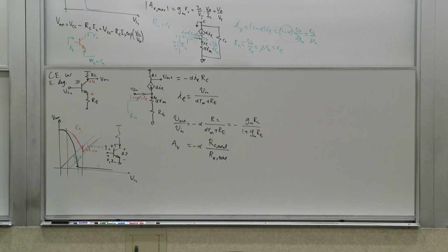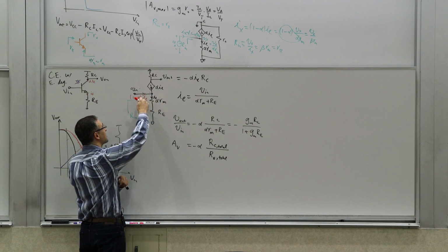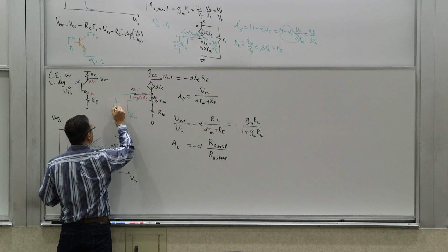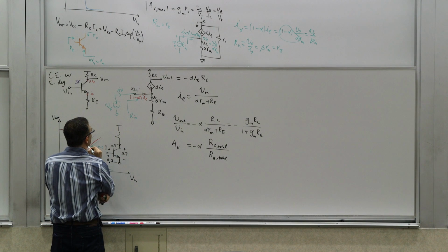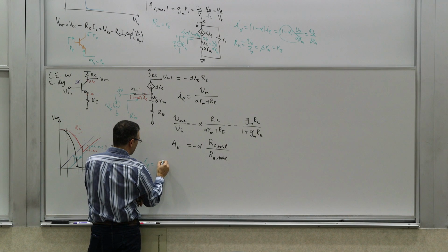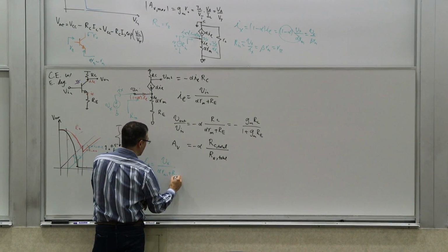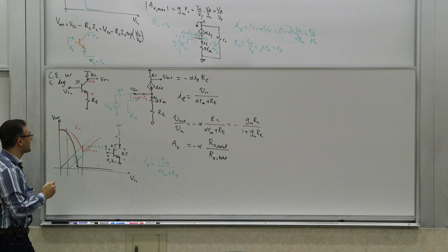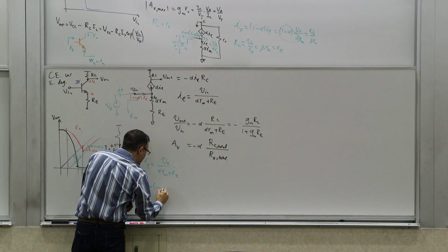Okay, so that's the current. So what does that tell? I have an interesting situation. You have this resistor, and the current through this resistor is clearly determined by this voltage. So if you apply a Vx here, let's say Vin becomes Vx, and you're trying to monitor what Ix is, Vin is Vx, therefore IE is going to be simply Vx divided by alpha Rm plus Re, the voltage drop across it. So that's IE. But the current that you experience, Ix, is going to be 1 minus alpha IE.